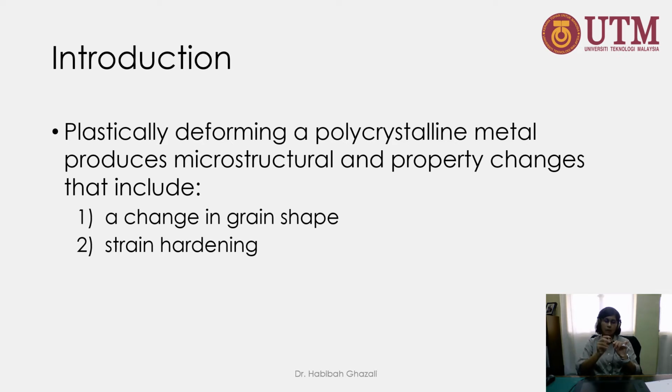If a second time I induce plastic deformation again, I actually need a stronger force to change it. Then the third time, a little bit stronger force is needed to bend it. If I try it again, every time it's going to get stronger and stronger. But eventually, it will start to break.